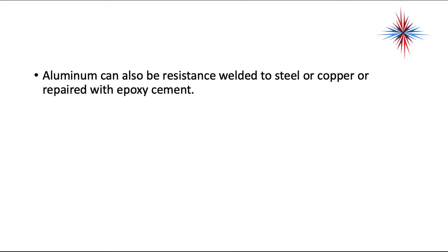It is not a good idea to perform long-term fixes on evaporator coils, okay? The fixes you do on an aluminum evaporator coil, if it's aluminum tubing, will not last long at all. It's because of the temperature changes that are constantly occurring, the movement from heating to cooling. The coils don't last very well once they're repaired.